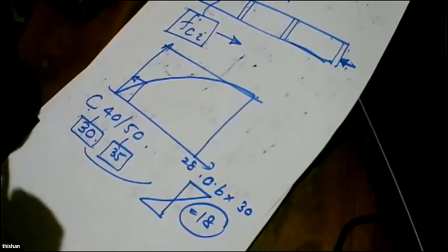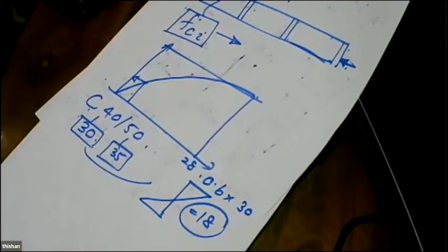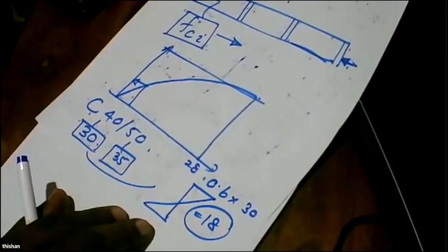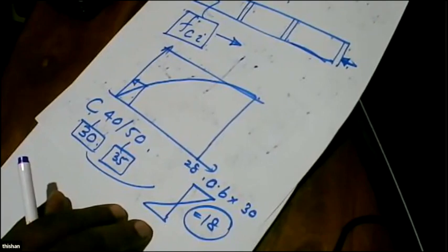strength. Because it's difficult for us to do that in a profitable way, what we do is specify a lower strength and say you can stress it at an early stage of strength development. So after about 7 days of casting the beams, you will find it has reached 30 megapascal.